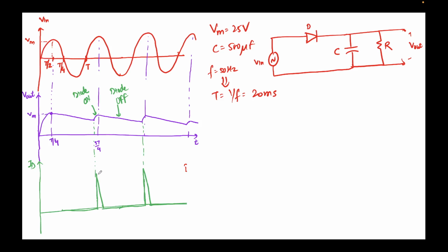And this is how the diode current will look. So you can see that the diode is off, so the current is 0 through this. So ignore this period for now, let's focus only here. During this part the diode current is 0, but at this junction the diode current will peak, rise sharply, and then gradually decrease, and here we know the diode will turn off. Why? Because now we have a negative half cycle, and the diode will clearly be reverse biased.